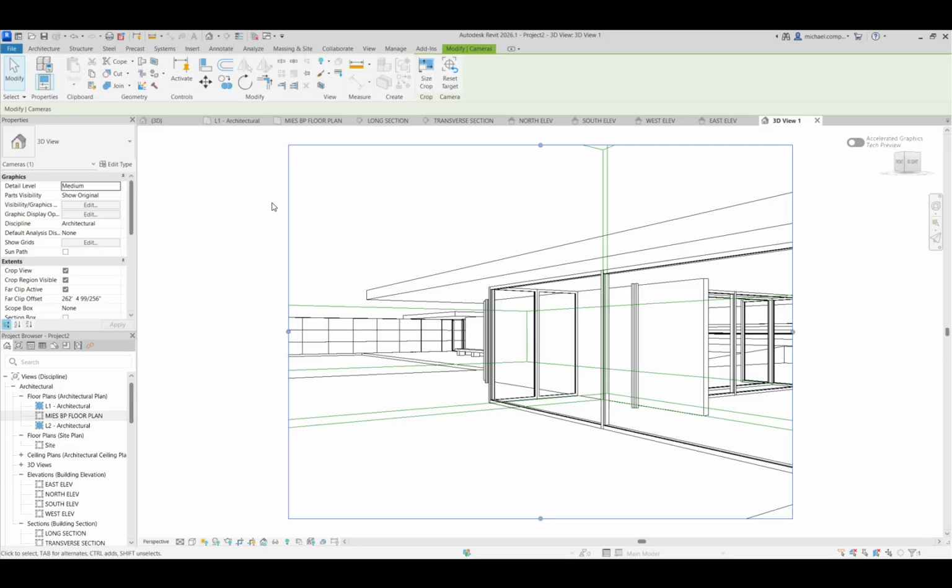Now, this is a Compton thing. I'm sure everyone who uses Revit perspectives does this differently, but the things I'm going to show you right now are presets that I like for using perspectives in Revit, because it changes in one motion. It changes the amount of information I see and the field of view or the camera angle. For the photography nerds, from going from a narrow angle to a wide angle, more like architectural photography.